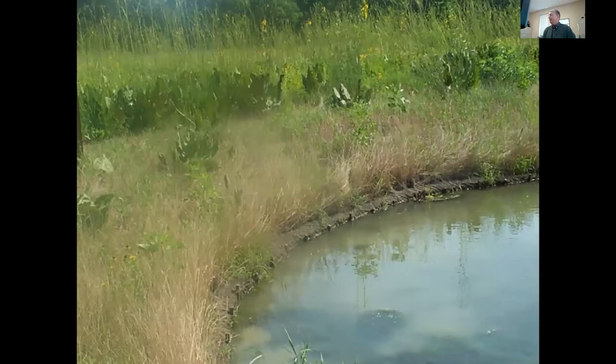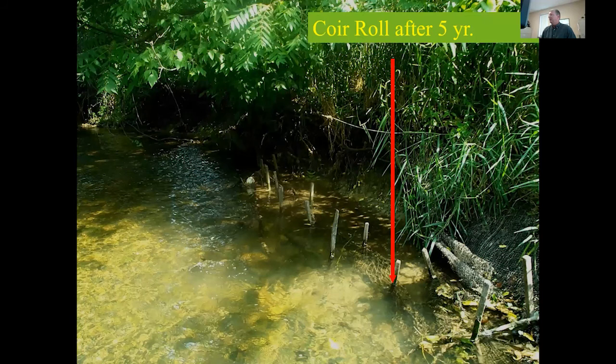So this is an example of a vegetative measure where we have a core log that's staked in place with wooden stakes, and there were some landscape plantings behind it, and those can be effective in some cases. And depending on the channel evolution model stage of the stream, those can be effective. One problem is, they're all usually temporary measures. So eventually you wind up just relying on the native vegetation for your protection again. And native vegetation wasn't preventing it from meandering or something before. So this is an example of a project after 5 years.